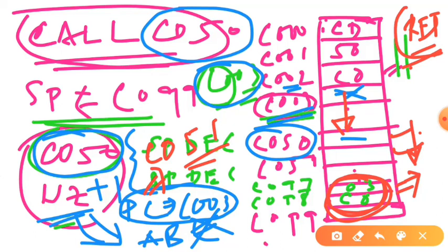As you can see, this is an unconditional call instruction. Therefore, whenever it is written somewhere in the memory location, the program sequence will always be transferred to the corresponding memory location, C050 or whatever the target memory location is. And obviously, before it shifts the program execution to the target memory location, it saves the next instruction's address in the stack, so that later on we can come back to that particular instruction, and we can fetch those instructions from that particular address.